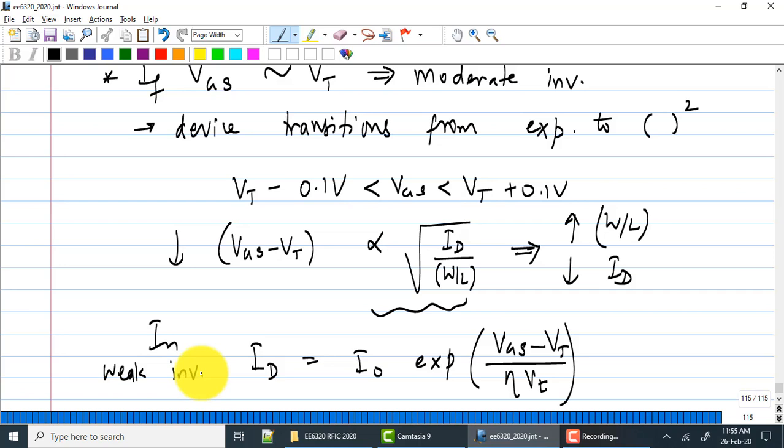What is the problem with this? You are now using an extremely large device with extremely small current. What is of course going to happen is that the capacitance of the device relative to its GM, you have to remember, how did you increase FT? By taking a very small device burning a lot of current. You have basically gone the other way. So you will basically have very, very low FT. You have now made the device have very large CGS, very small GM. So the FT of the device will be extremely small.